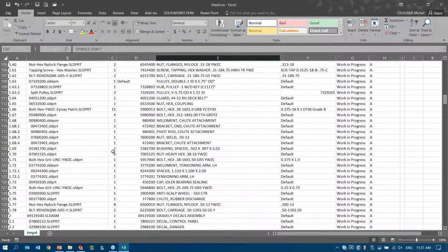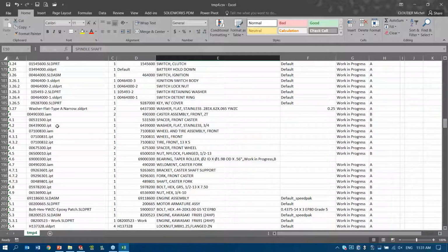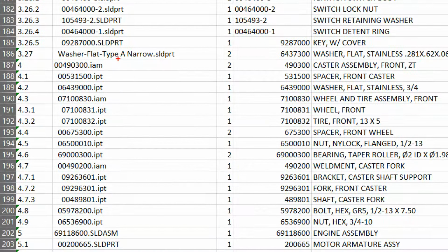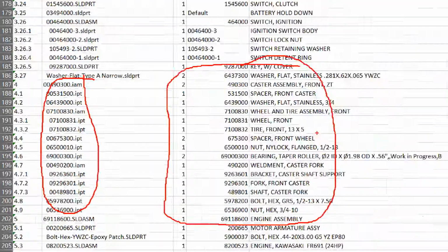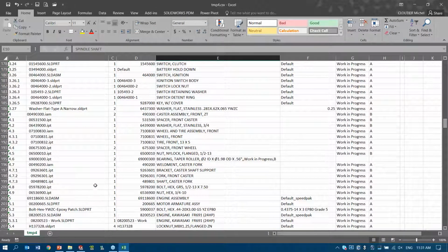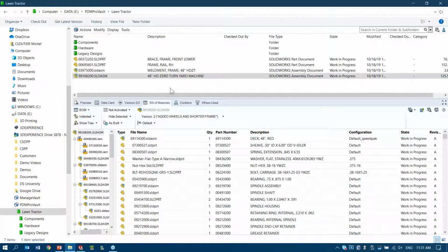So it actually created that bill of material right from my assembly, including all the Inventor components in here with their description, their quantity, their part numbers. So even though these files are native Inventor files, we read all the information within the Inventor part file and the assembly files: the properties, part numbers, and we'll calculate quantities, obviously, and all of that. So very easily, I can manage all of these designs right inside of my